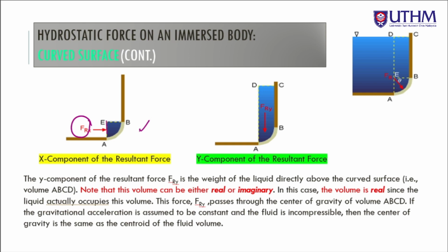Okay. So on the other hand, for the FRY, or the Y component of the resultant force, is actually the weight of the liquid directly above the curved surface, which is this one. That is the volume of A, B, C and D. Note that this volume can be either real or imaginary.